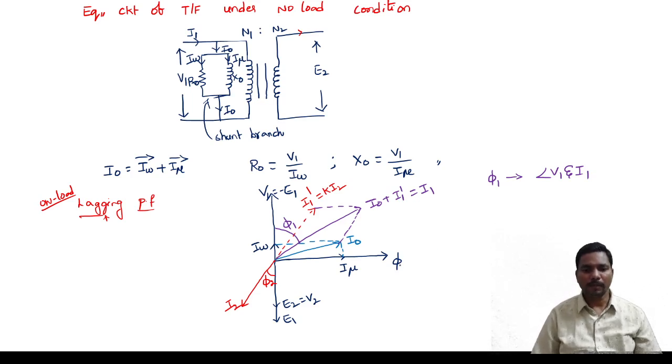First of all, I have drawn phi, and the voltage is leading. If you apply the voltage, flux is produced. After the flux is linked with the coil, EMF is produced. Just taking the current as lagging, I am extending it on the other side. I am taking it as I1 dash, that is equal to K into I2. The vector sum of I naught and I1 dash is nothing but I1.